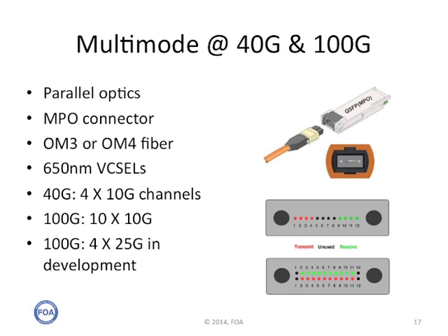There is a version of 100 gig being developed for multimode that uses 4 25 gig channels, which is expected to have a shorter reach than the 10 channels. The design should use a connection scheme like 40 gig on the 12 fiber connector. Multimode transceivers use inexpensive 850 nanometer VCSELs, so transmitters are cheaper, but the cable plant, which uses so many multimode fibers, is more expensive.